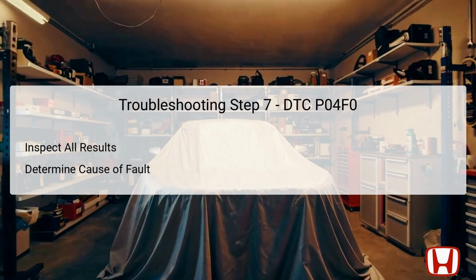In the final diagnostic step, analyze all results acquired from the previous inspections. If all other components performed normally, the focus should shift to the evap canister purge nozzle itself. Should all its inspections reveal no issues, yet the DTC persists, it is likely that the nozzle may still be at fault. A malfunctioning nozzle can show normal operational signs, but may fail under dynamic conditions.